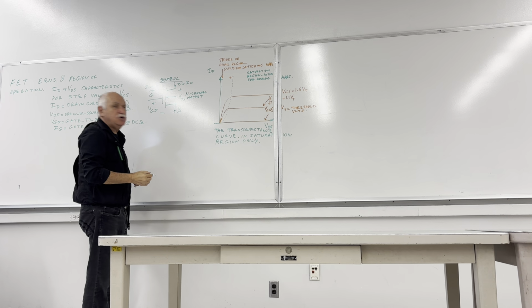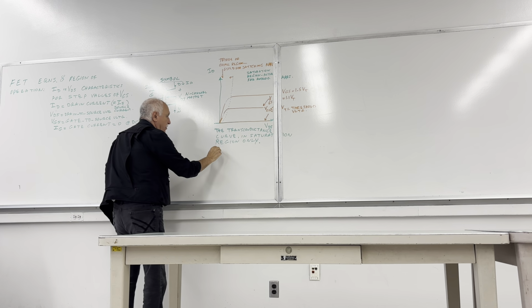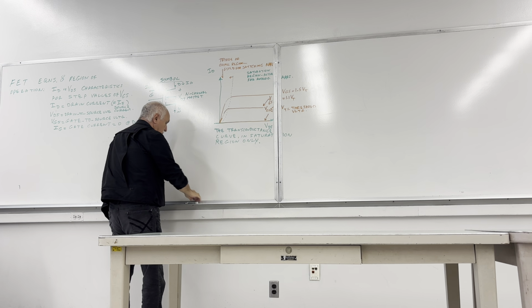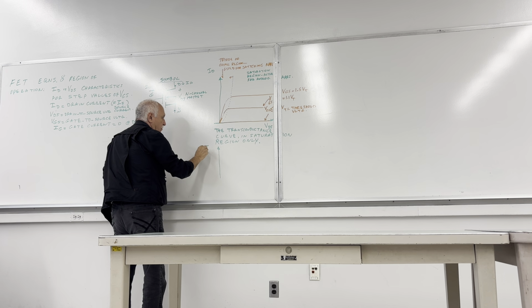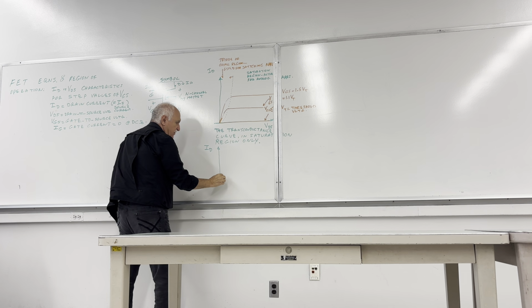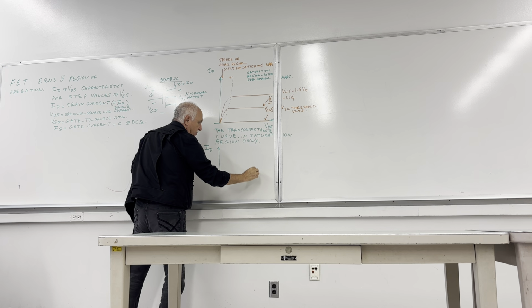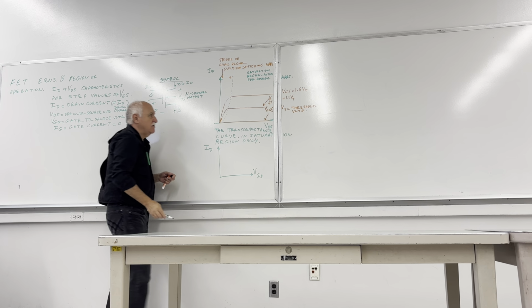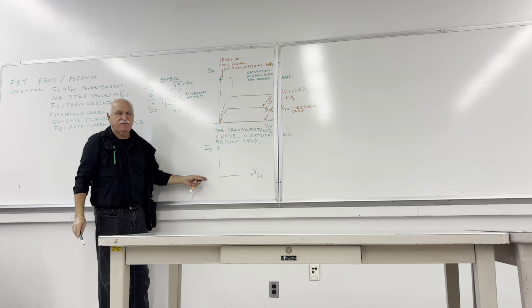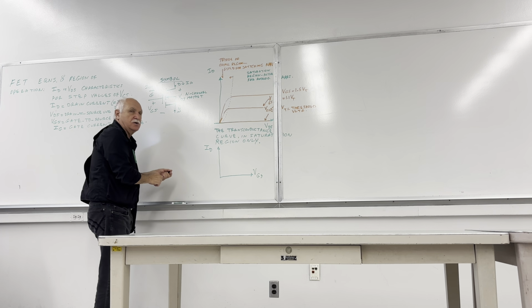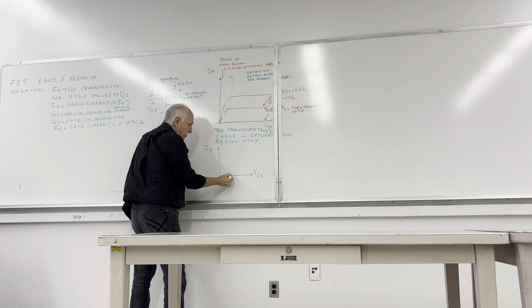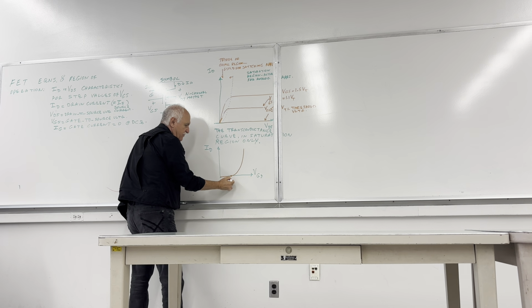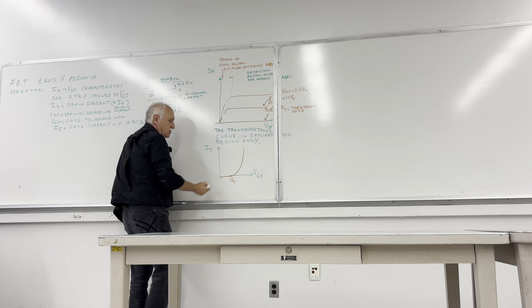This transconductance curve looks like ID as a function of the VGS. VDS plays no role in this function. The curve resembles a parabola that starts from a point called VT, threshold voltage.